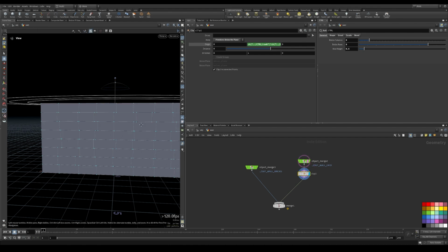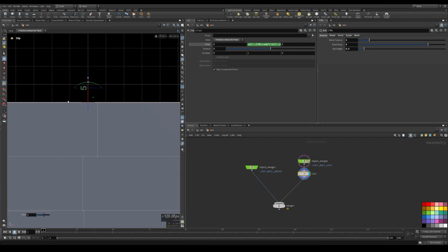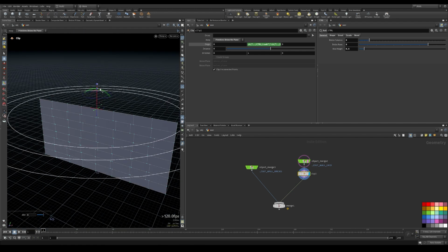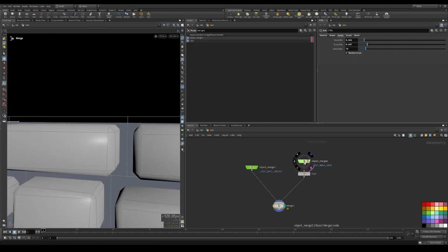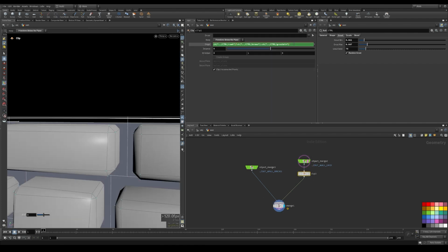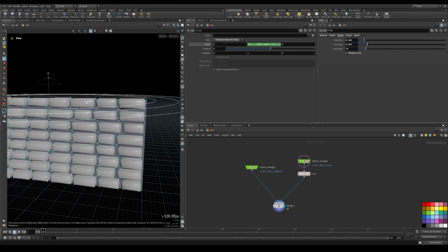So now we have basically the total height of our brick wall, and we need to subtract the grout amount, and we want to take the minimum value. So copy parameter here and subtract it at the end. So we need to add a little more, and we just want to multiply the grout min by 2. So we end up with something like this.